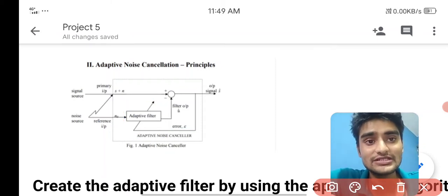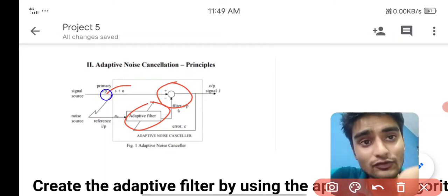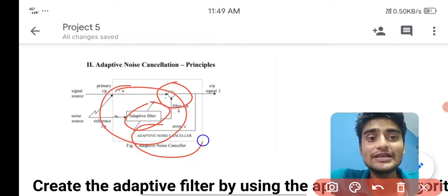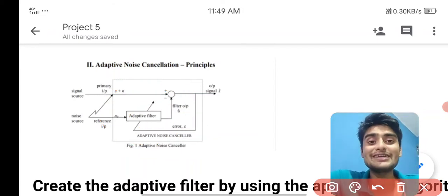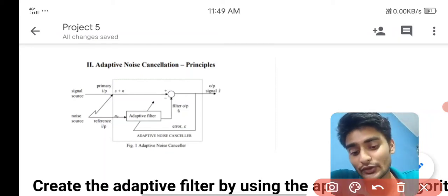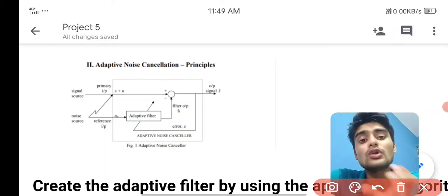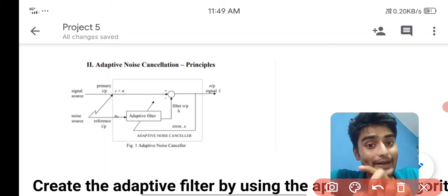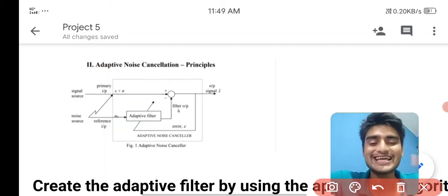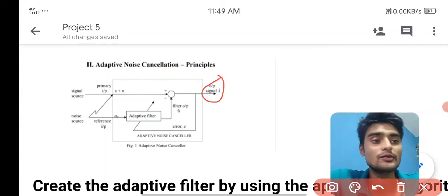When adaptive filters are used, we should have a summing point, because we have to do these operations in the filter itself. There is an advantage of using LabVIEW programming: whenever we use filters, if you double click on the filters, there are sub VI programs. The inbuilt programs we should not change; we only have to double click the filters and change the frequency, amplification, and phase angles. That is what we have to keep in mind for a fruitful output of the signals.